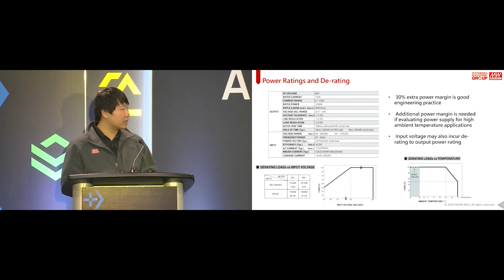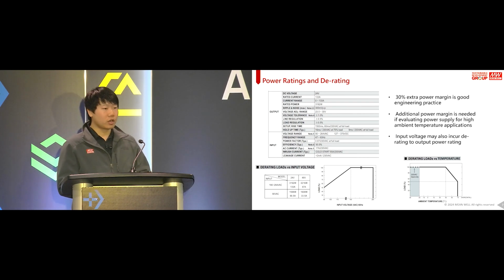So here's a snippet. It may be a little bit small, but it's a snippet of one of our product specs. And we will tell you the input voltage, the output current. So these are very important values in determining how big your power supply needs to be. And it's also very important to consider derating for your application. So general recommendation from the power supply manufacturers, of course, we recommend to leave at least 30% margin for power supplies. So if your application requires 100 watts, it's generally best to go with 130 watts of power supply or higher so that the power supply has long lifetime longevity and also reliability is ensured.